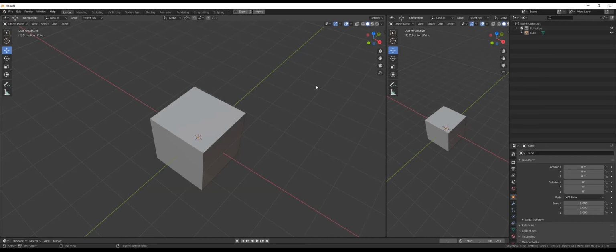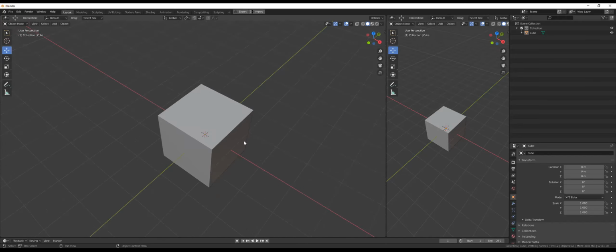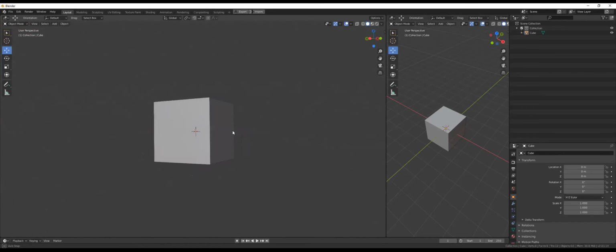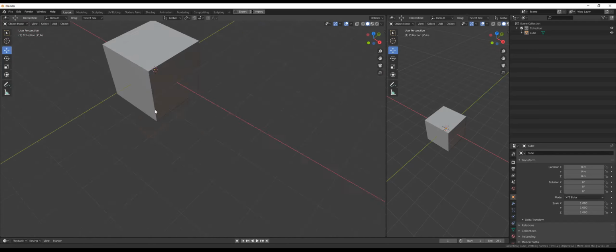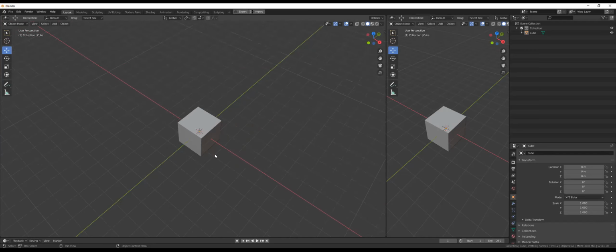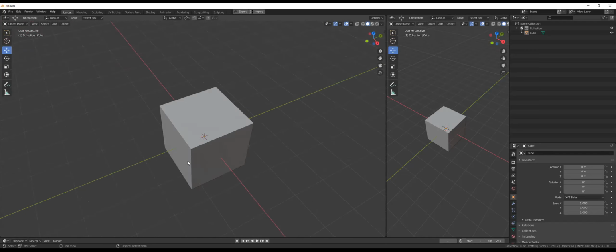When you open it up, it's immediately open, and you can start modeling immediately. You just turn on the functions you're using or need. So again, for me it's Alt plus middle mouse for rotation, middle mouse for pan, and the wheel is zooming in and out. I use this setup.